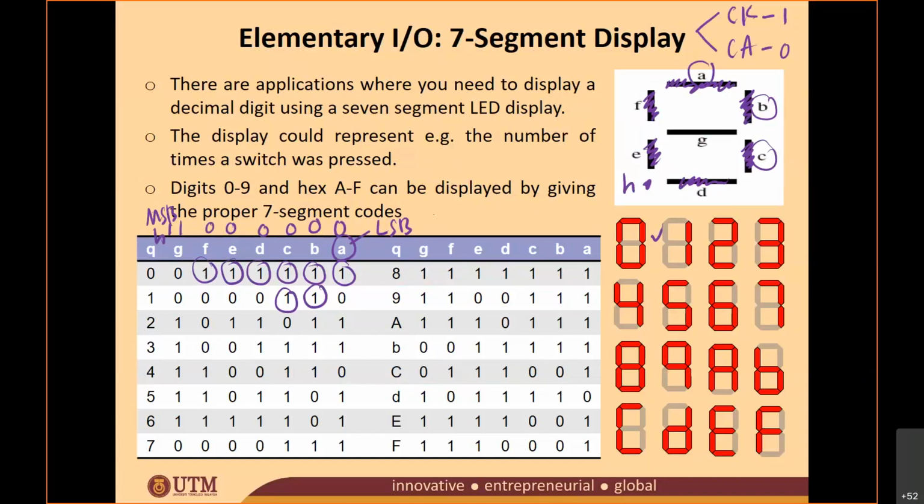Make sure that you identify what 7-segment display you're going to use, either common cathode or common anode. Based on this common pin, you can figure out the value to put to your LEDs to display the numbers or certain characters.